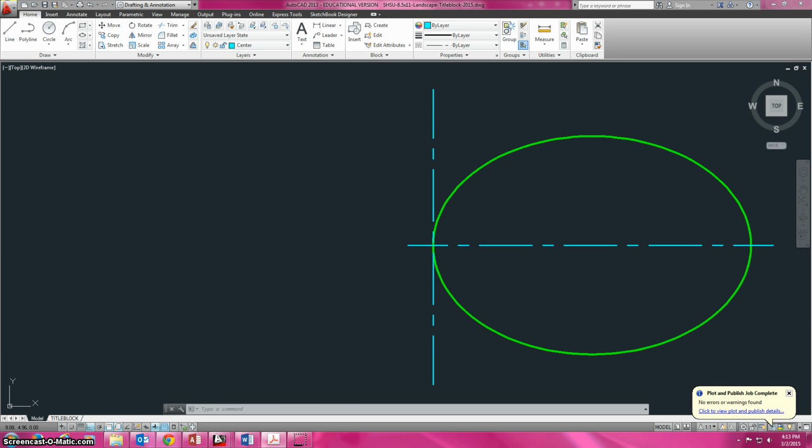So I'll go look at the drawing, and I'm going to offset per those dimensions. I look at the drawing and I see, what does it say? Well, it says the first one's 1.5, and the next one's 0.75, and so forth. So you have to be able to read the drawing. So I'm going to offset it, type in the distance,